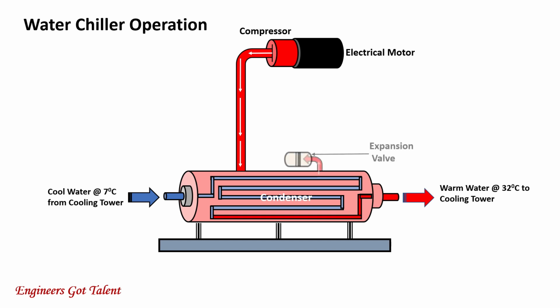From the condenser, the warm liquid refrigerant enters the expansion valve at high pressure. Expansion valve is also called a metering device. This valve regulates the flow of refrigerant going around the chiller. Its function is mainly to reduce the pressure and temperature of the refrigerant. Because the valve restricts the flow, less refrigerant will flow to the evaporator coils. Thereby, there is more room for the refrigerant to expand. This is called flash vapor.